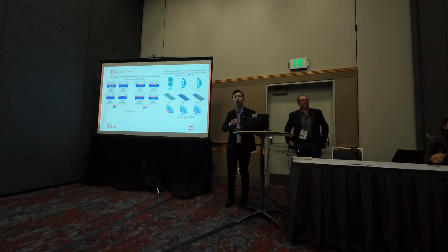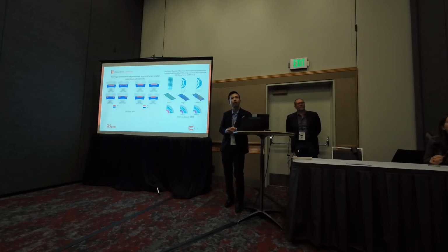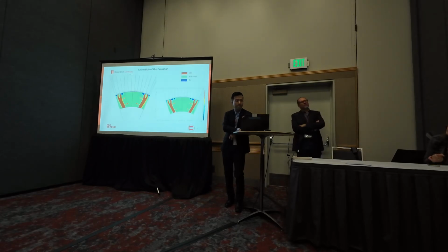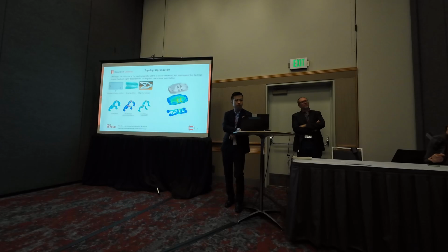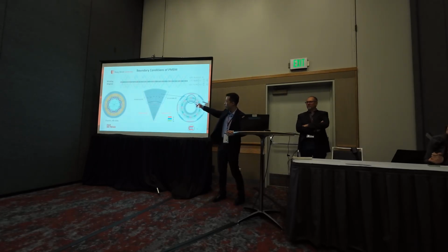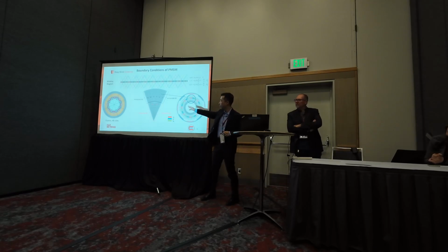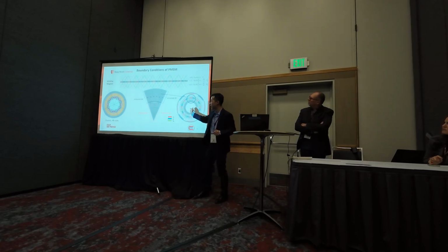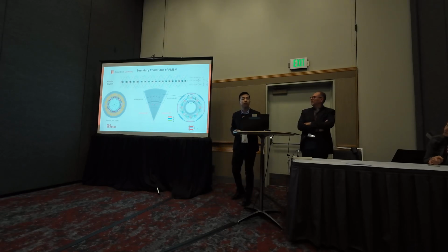This might be a really dumb question because this isn't my field. You chose to use the 8 sectors, and then you just chose one and worked with it. Is there any sort of interaction between the sectors? That's why we apply the anti-parallel boundary conditions. For example, if this magnet pole is a north pole, with the anti-parallel boundary conditions, the next sector will be the south pole, in order to reduce the computational cost.